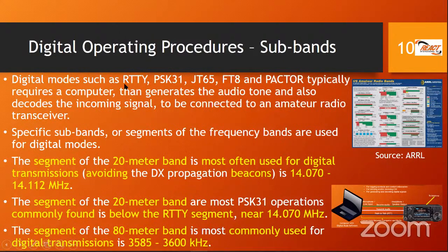And some of those digital modes are RTTY, radio teletype, PSK31, JT65, FT8, Pactor. Those are the typical digital modes that you'll hear about. There are many, many more than that, of course. But they all rely upon a computer connected to the transceiver to generate those audio tones and to also decode and display the incoming messages on the computer screen. So when you hear digital mode, think computer connected to your radio.